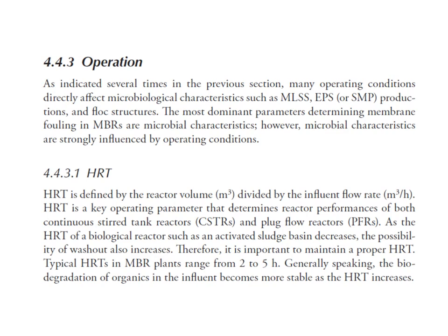As we have already mentioned, many operating conditions directly affect microbial characteristics such as MLSS, EPS, or SMP, and floc structures. The most dominant parameters determining membrane fouling in MBR are microbial characteristics.